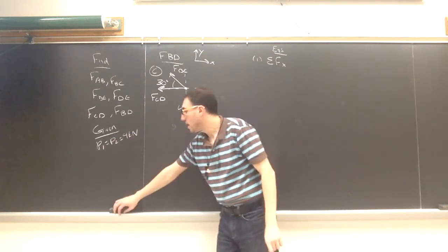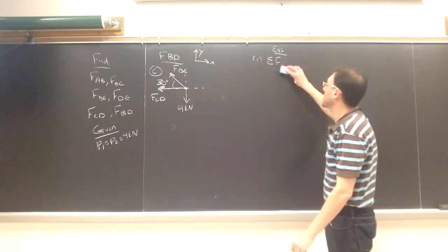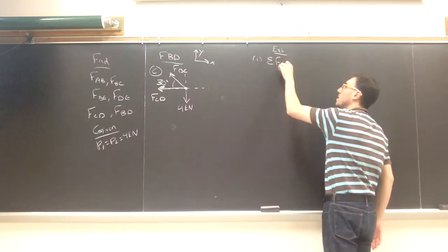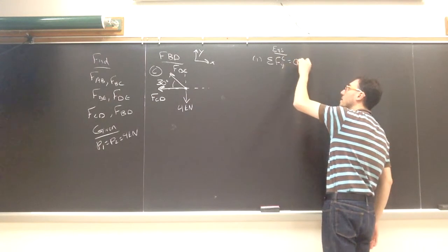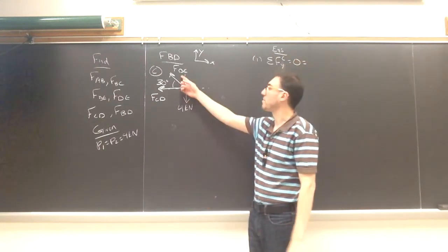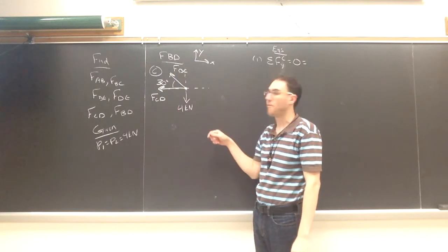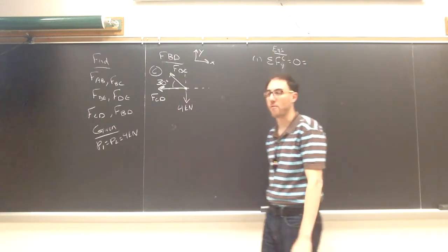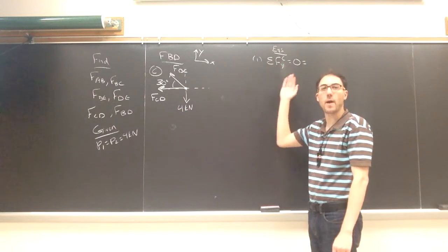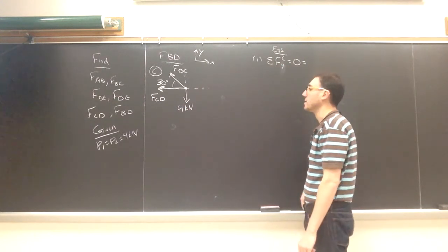And actually here, I'll start in the y direction in picture C, because looking at this picture, BC is the only thing that has a component in the y. So I'll be able to solve for a number right away, right from my first equation. If I started with x, though, I would just come back to it to be able to solve for a number.